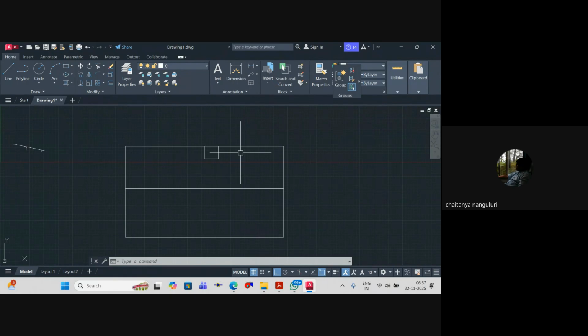So, according to the beam layout, you will place your detectors. If the space is greater than 800 mm, you do; if it is lesser than 800, you need not install the smoke detector. That is clearly mentioned in the IS code, which I'll be showing you shortly. Understood?